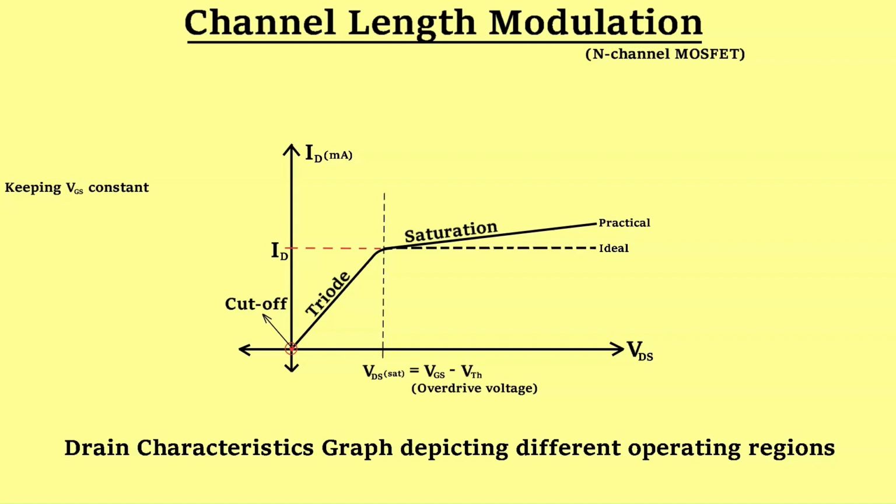Remember, MOSFET is a symmetrical device. When we apply a negative drain to source voltage, then the roles of drain and source will reverse, but there is no need to draw that. Just keep this in mind. The graph exists only in the first quadrant. I am just writing symmetrical just to signify that we have considered only positive drain to source voltages.